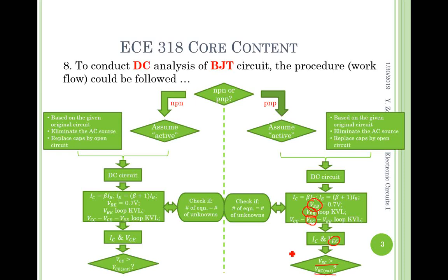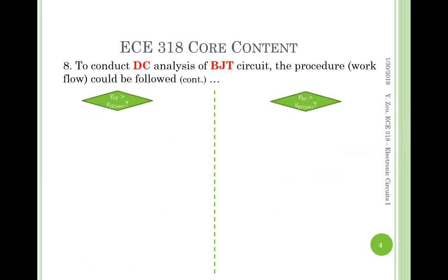Here I want to emphasize one thing. Both the VCE saturation voltage and the VEC saturation voltage are small voltages. Generally speaking, they are available from the data sheet of any particular BJT, and they are very small, so it's not very easy to become saturated. Okay, so going back to the NPN BJT route,